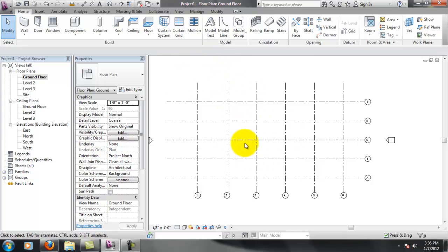So now that we have these grid lines, we can go ahead and start dropping in some columns. Now, that would be the next step, and I know most interior designers and architects hate dealing with columns because they usually end up right where you don't want one. So I'm going to force this class especially to use grid lines and columns just to keep it a little more real world and a little more practical. Revit makes it super easy to add columns. It's not a hassle, especially if you have a rectangle building like we have here. We're kind of fortunate to have this shape because it's going to be easy to add columns.